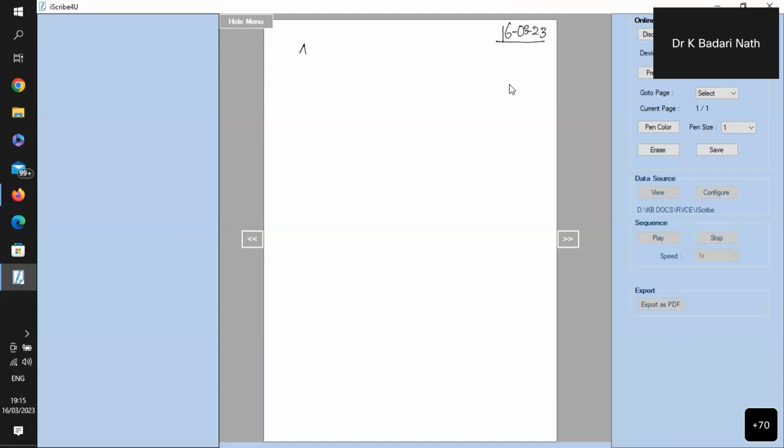So we will start discussing the different addressing modes supported by, in general, any processor. We have discussed the 5 addressing modes supported by the processor. The first addressing mode is, as we learned, the immediate addressing mode. The example we studied is, if I want to move the number 20 into any of the registers, it becomes an immediate addressing mode. The second addressing mode is called the register addressing mode.